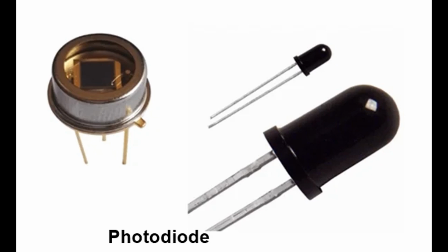Summary. In essence, a photodiode detects light by converting incoming photons into an electrical current. The P-N junction and the depletion region play a critical role in separating charge carriers generated by the light, creating a current that is proportional to the light intensity. Depending on the mode of operation, photodiodes can be used in a variety of applications, from slow solar cells to high-speed optical communication devices.